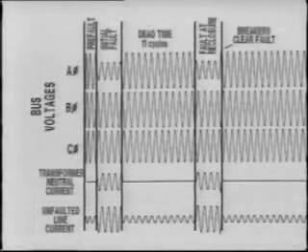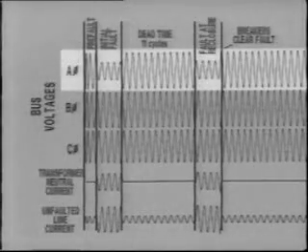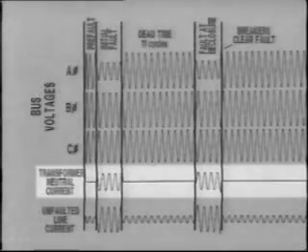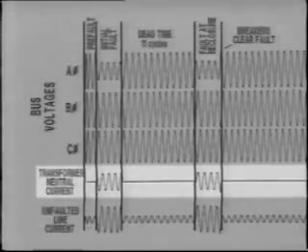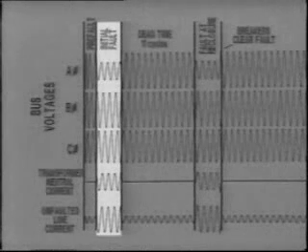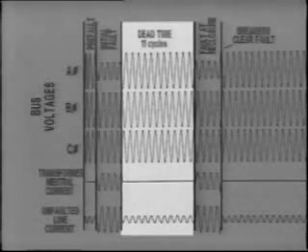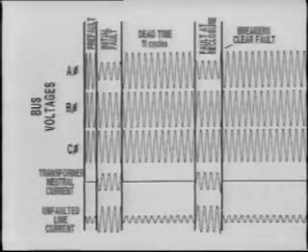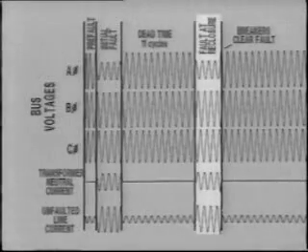From the bus voltages, we conclude that the fault is a single line-to-ground fault on A phase. This is confirmed by the transformer neutral current. We can also tell that the fault duration is 4 cycles, and the line dead time is 11 cycles. At this point, the breakers on the faulted line reclosed, but the fault was still there.